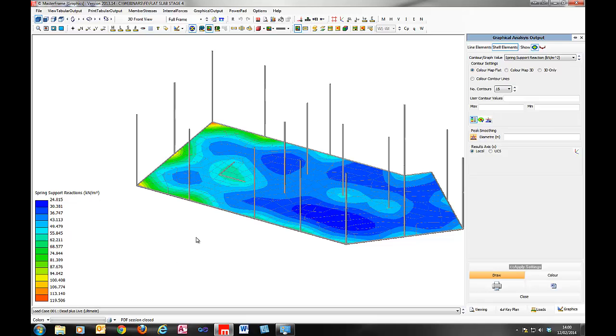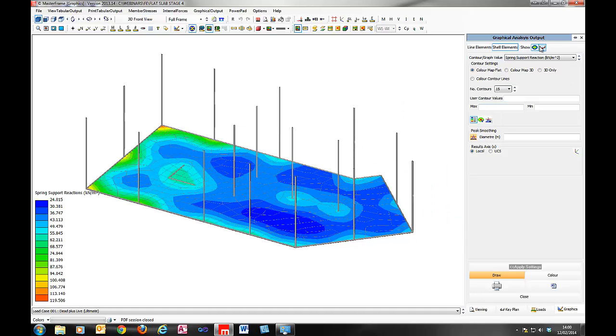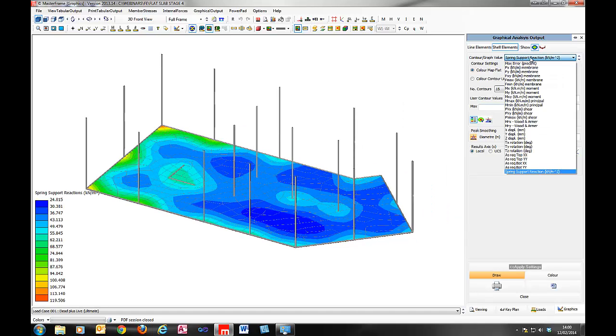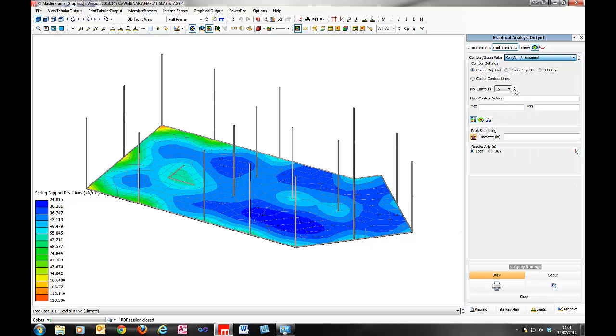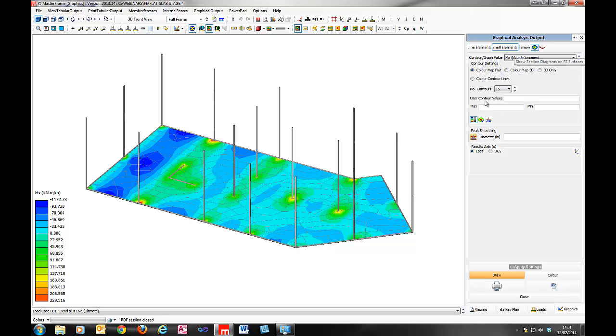That obviously is giving you your ground bearing pressure essentially underneath the base of that raft. And otherwise the design of the raft for the areas of reinforcement is exactly as you would do for a normal flat slab arrangement. You're still going to use your values of contouring of reinforcement and your section diagrams for that type of thing.